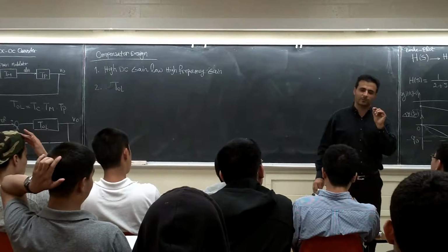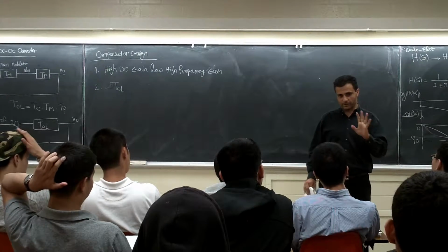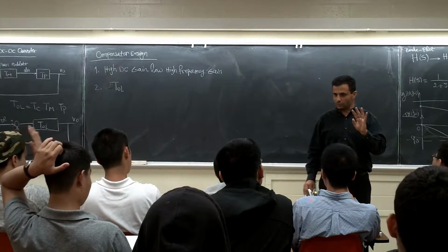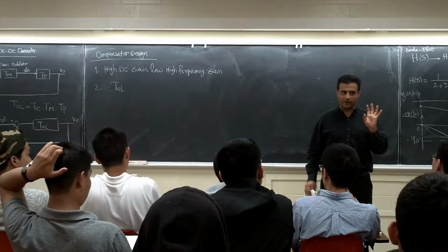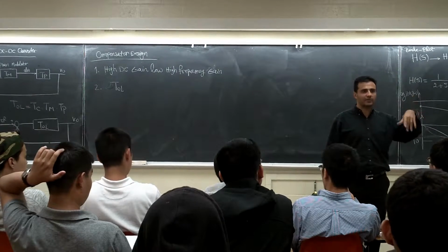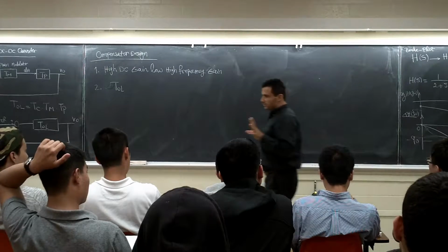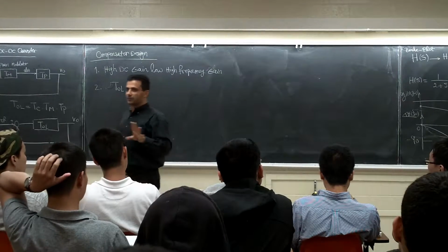And we start to change it, like, okay, change KP this much. Not blindly, there is a point behind how to change it. We bring the KP, KI a little bit more or less, and look to see when we're going to get the best performance of the system. Because at the end of the day, these systems are very nonlinear.